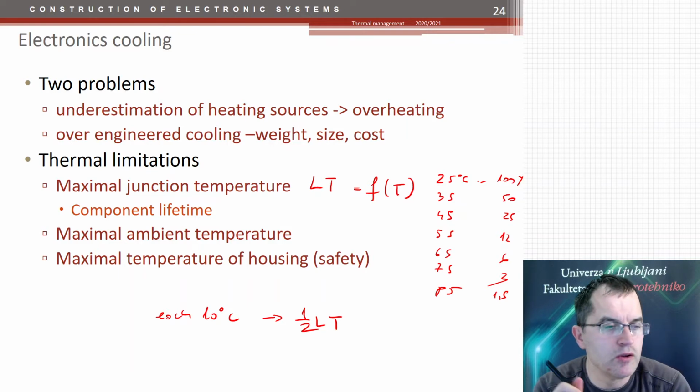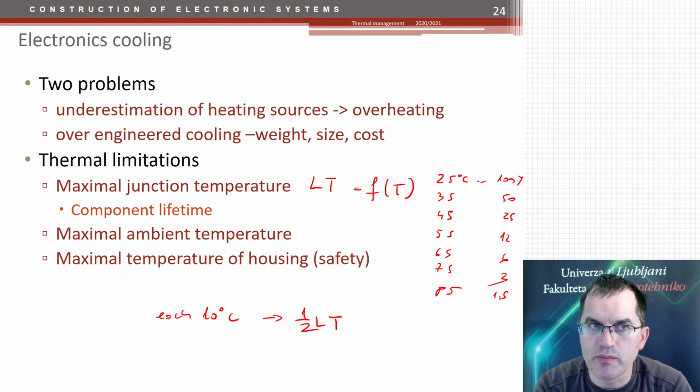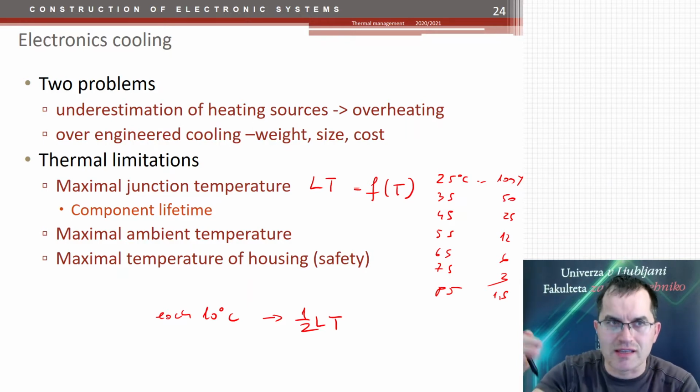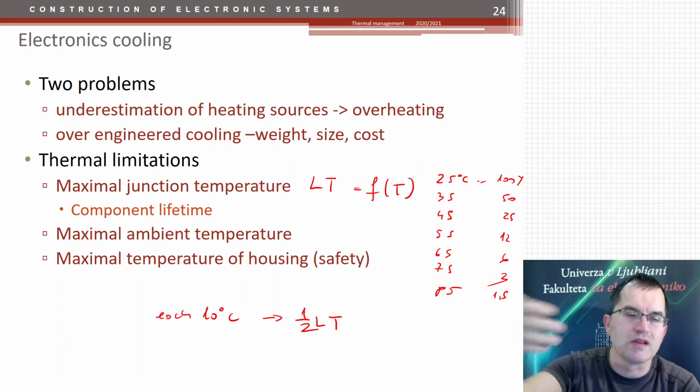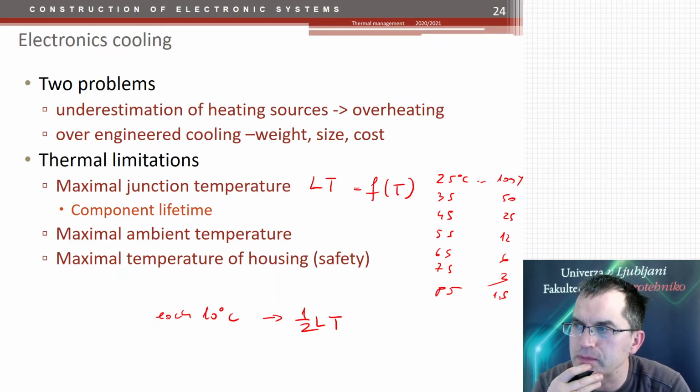And even if you use a device on your desk, usually in your office, let's say a laptop, for a certain component you have to count the internal temperature of the laptop, not the external one. Because for these components, the first cooling would be from the PCB to the surrounding, which is still inside the laptop, and then cooling towards the air outside of the laptop.